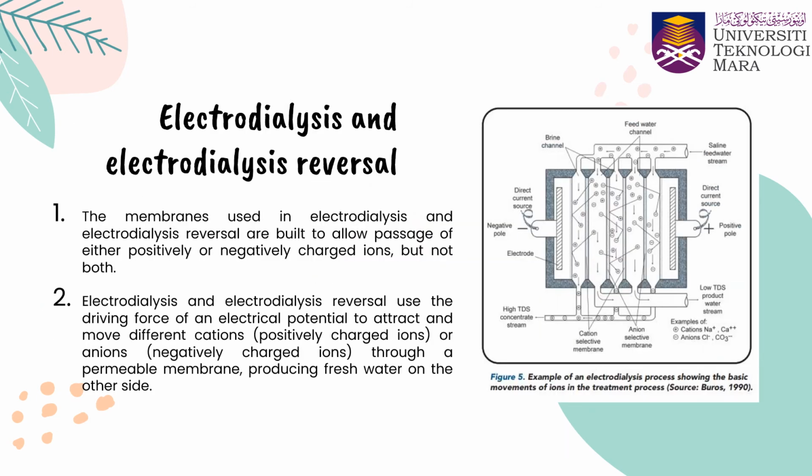Next is the method of electrodialysis and electrodialysis reversal. This method is built to allow the passage of either positively or negatively charged ions. Electro is related to ionization. Both electrodialysis and electrodialysis reversal need a driving force, or electrical potential, to attract the opposite charge.